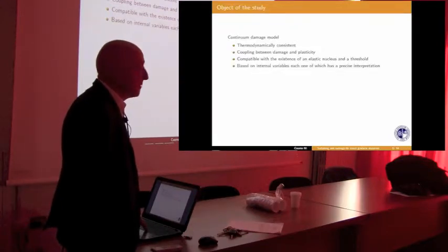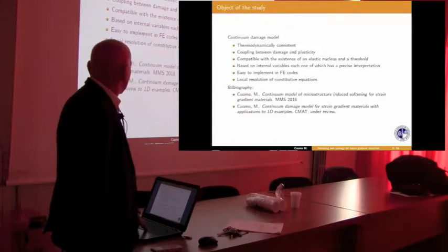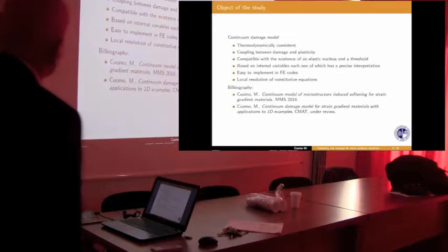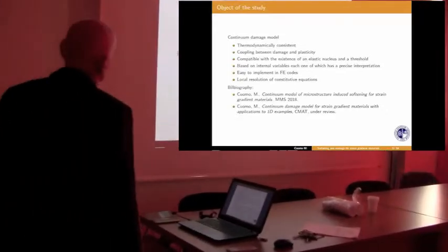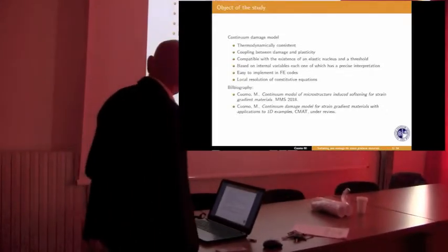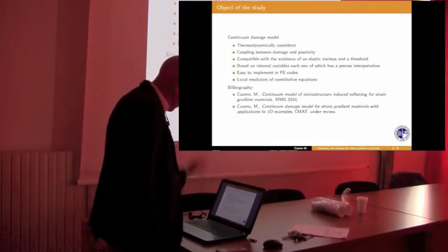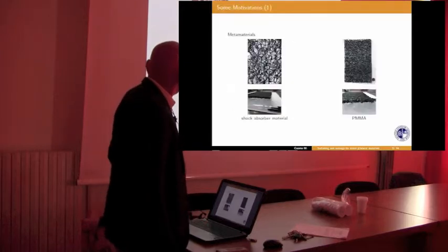It's based on internal variables, each of which may have a sound physical interpretation. It's very easy to implement in finite element codes. And the most important thing is that the constitutive equation can be solved locally, even though the model is non-local. So there are two papers about this subject.